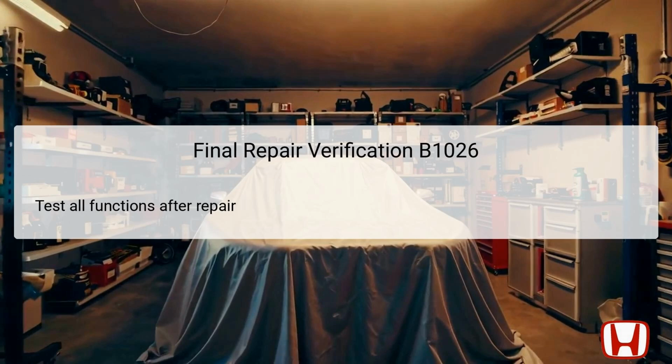After conducting repairs for the DTC B1026, performing final checks and tests is essential to ensure that all functions have returned to normal. This verification involves operating the passenger's door lock switch multiple times to confirm that the locking mechanism is working correctly. Additionally, testing the keyless entry system is imperative, as it is integral to ensuring the entire locking system functions seamlessly. If any issues persist, further investigation into the underlying circuit and components is necessary.